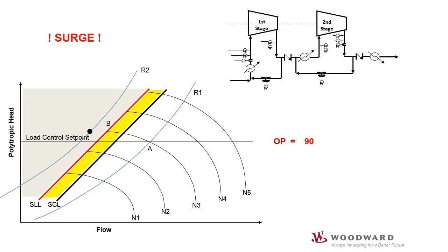Did you notice that the moment we cross the red line, the operating point was much below 100? That's the distance which we defined, how deep we want to go from the surge control line to the actual configured surge line. So at this level, we are familiar with the basic concepts of anti-surge controller.